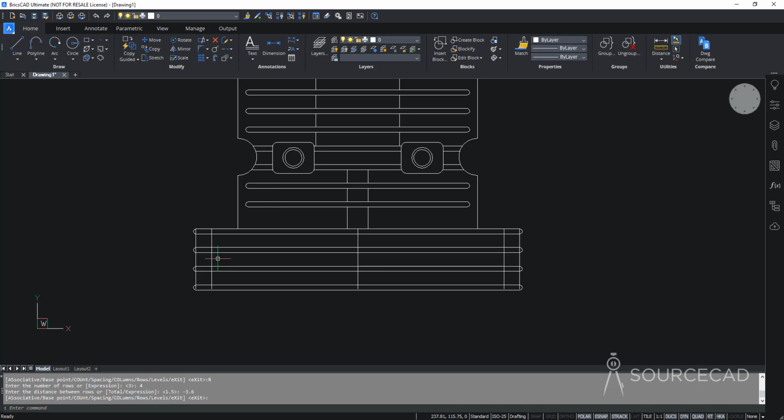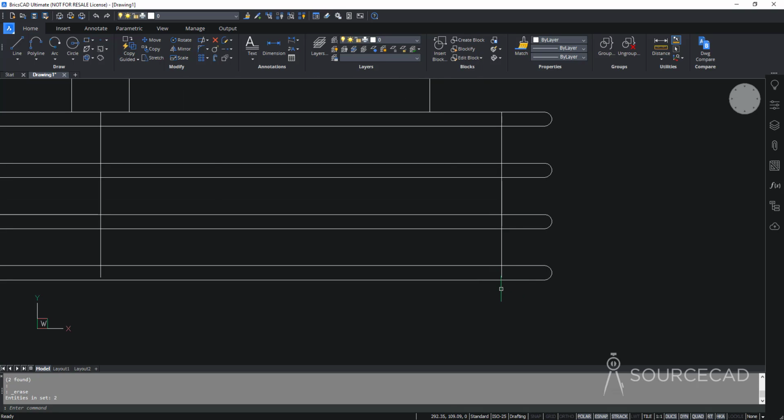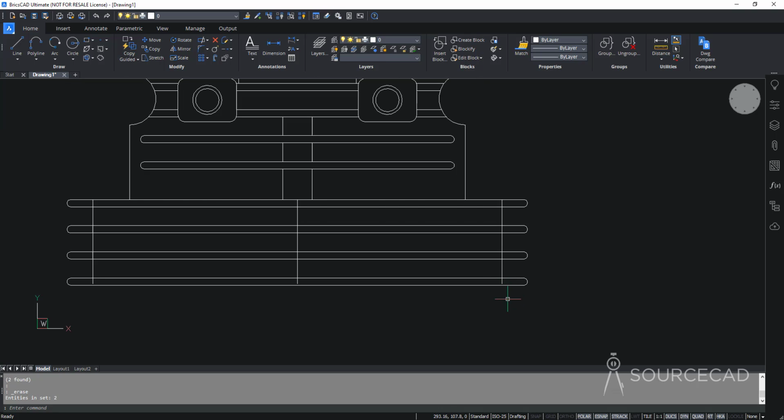So now that we have added here, we can delete all of these construction geometries. So this, and I'll just leave it for now, but these two I'll delete. And there is a tiny gap here that I'll merge, so using the extend tool, we'll use that as well. But for now, all these construction geometries, we can just get rid of. And now I'll go to extend, which is right here, press enter. I'll extend this line, I'll extend this line, it will extend up to the next boundary, which is right here.